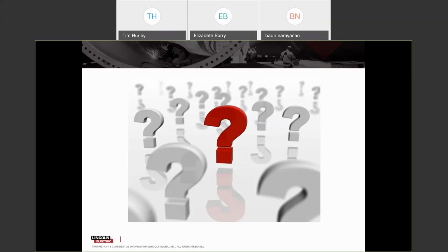So that's a good question. I didn't go power source side of things because we're really looking at weld deposit, but the RapidX waveform is available on any of our Power Wave machines. The RapidX waveform does require an STT module, so there are a certain number of our Power Waves that are compatible with the STT module.